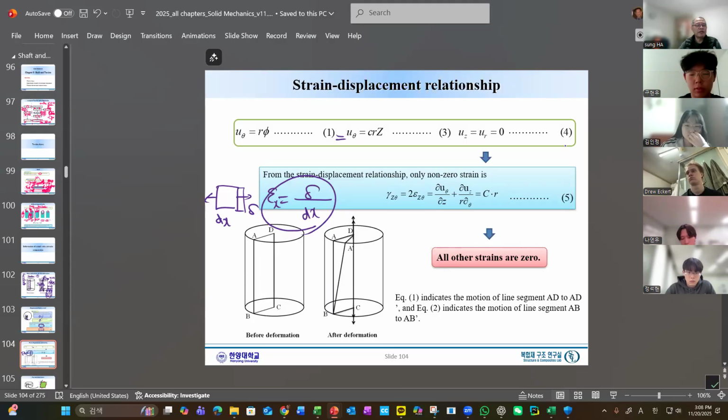This is actually the derivative with respect to x, the partial differential way of expressing a strain. The shear strain is very similar, with the displacement and the z. This is the original, and this is the original. This guy is the extension. But rather than extension, this will change the angle. So that's the big difference between the extension and the shear.